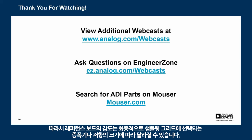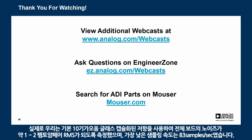The sensitivity of the reference design board depends on a couple of things, like the amplifier, the size of the resistor that you eventually end up using, and the sampling rate of choice. In the lab, we measured the noise of the entire board to be about 1 to 2 femtoamp RMS with the default 10 gigaohm glass encapsulated resistor and with the lowest sampling rate of 0.83 samples per second.